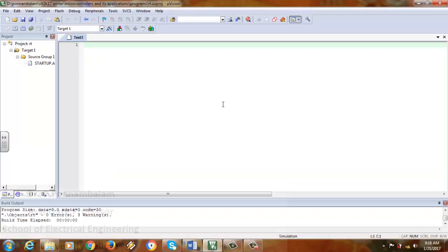Okay, now as we have done earlier, we'll have to move DPTR with #4500H, that is the starting memory address, and we'll assume that 4500 is going to be the input memory address.